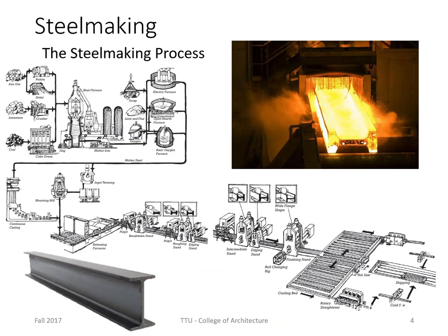And those are what you don't want to add to the steel. So they run it through this coke oven, and that produces pure carbon. The coal that comes out of this is called coke because it doesn't have any of the impurities that normal coal has in it. It's just pure carbon, which will get hotter and create a more pure fire. Then those three things are mixed together in a blast furnace, and this is where we begin to make cast iron.